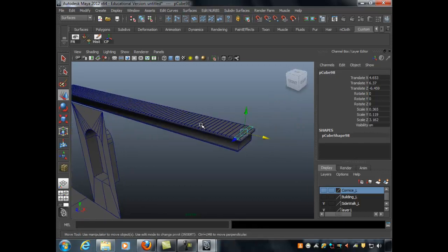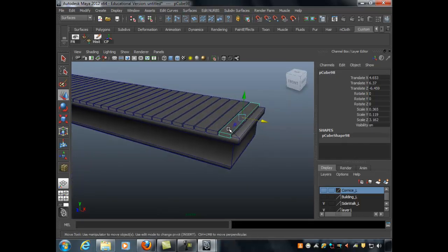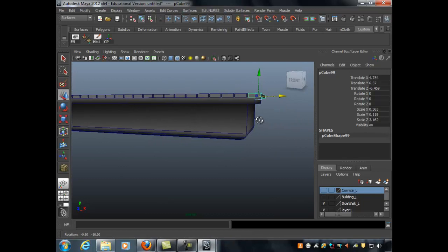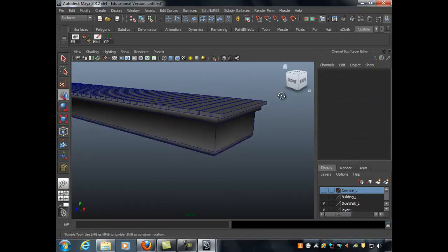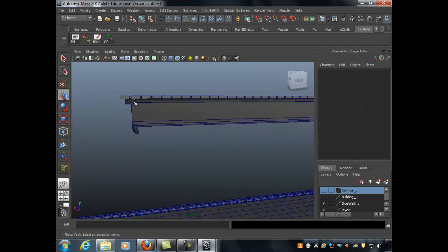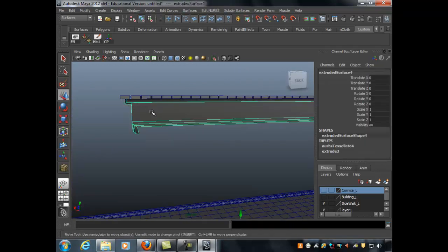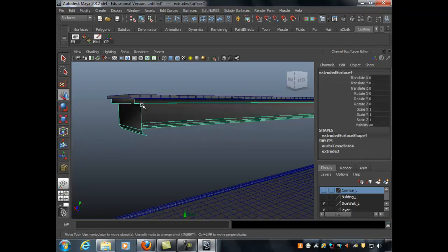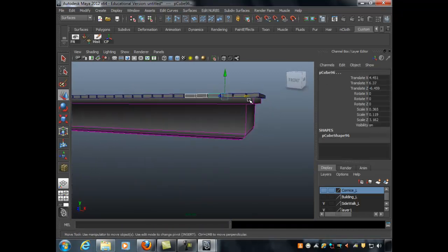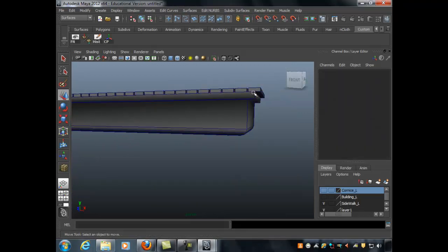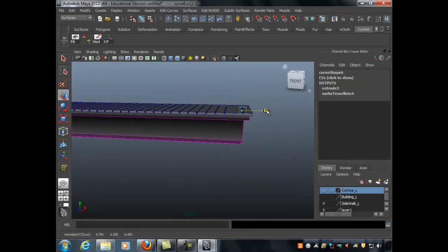And then the cool thing about this is, see how it's a little long right there? When I created this using the loft, so this is good for you, Christina. You were talking about box modeling before. But one of the advantages of using the NURBS tools is that you retain this construction history on everything. So if I go to Control Vertex here, see how I can move?